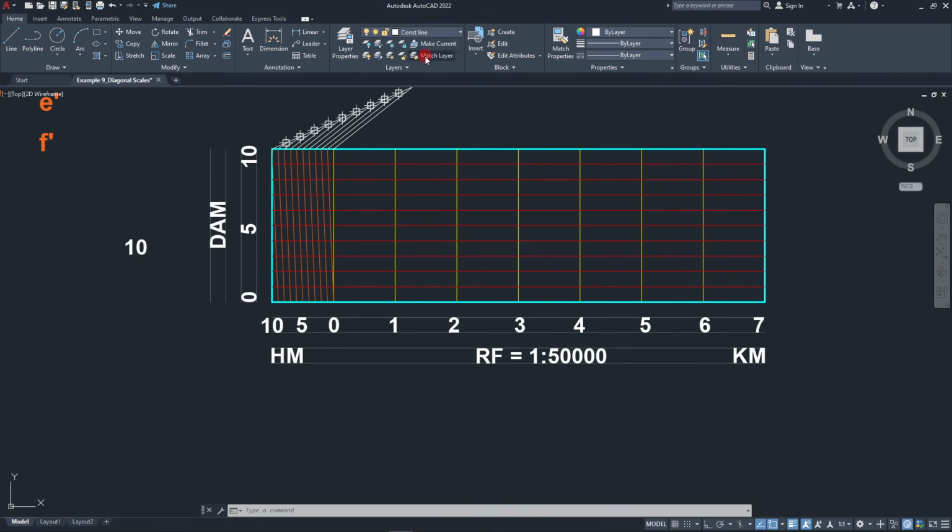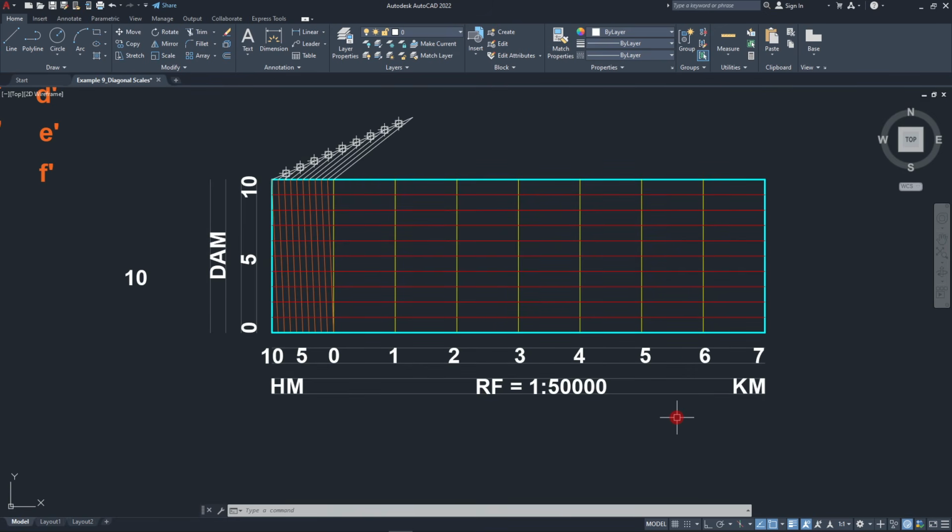This is the construction line, so see, the transparency has increased, right? Your work can be made very easy when you are working with layers. In fact, I already had this solid thick line. I could have just selected all of these lines and then changed its layer. That would have also been the case.